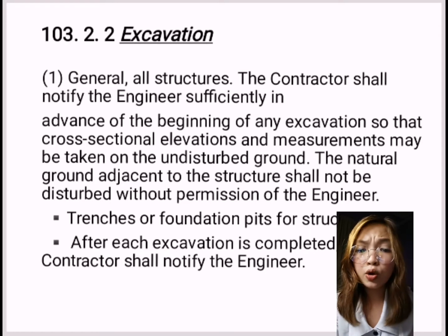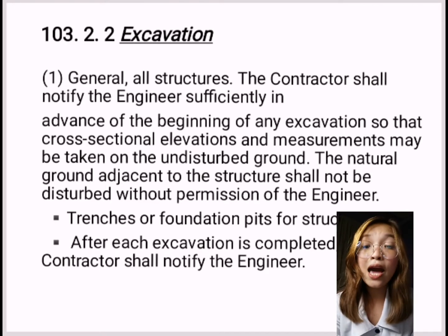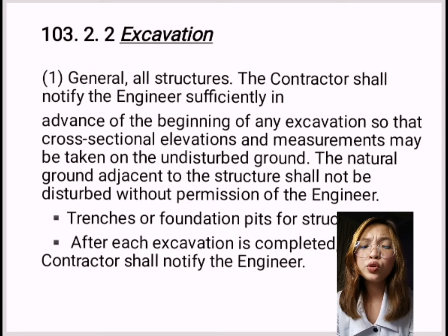So, trenches or foundation pits for structure or structure footings shall be excavated to the lines and grades or elevations shown on the plans or as staked by the engineer. So they shall be of sufficient size to permit the placing of structure or structure footings of the full width and length shown.